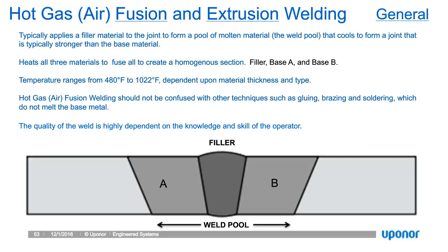The weld seam will have more material, will be a thicker section, and when we run it through tensile strength testing, our expectation is that the other material, either the A or B materials in the system, will fail and not the weld itself. So with this, we're able to create a huge array and an infinite configuration of different types of systems by use of extrusion welding and polyethylene. Much like you can think of, we can weld almost anything and create almost anything out of steel. The same would apply to polyethylene, where we can create almost anything out of polyethylene using thermoplastic fusion welding.